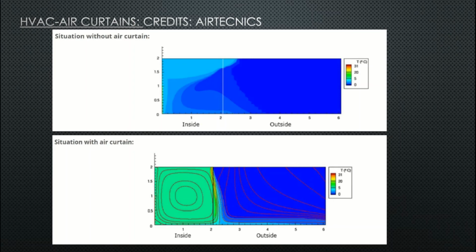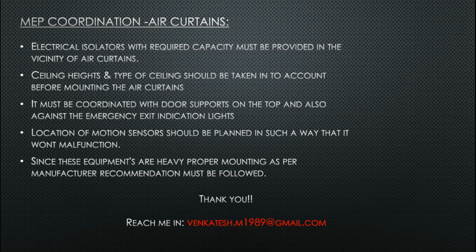Let us jump into the important coordination aspects, or MEP coordination aspects, of air curtains. These air curtains are operated by motors. So whenever there is a motor, we have electrical supply. That acts as the first coordination between mechanical and electrical services.